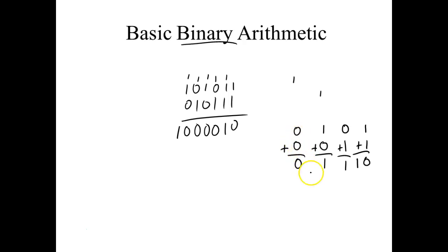So what circuit would give us this right here? So what we're going to do is going to do away with the carry. So when they're not equal, I get a 1. When they are equal, I would get a 0. So let's see, I come up here and I put a 0, 0. What's a 0, 0? This is the exclusive OR.